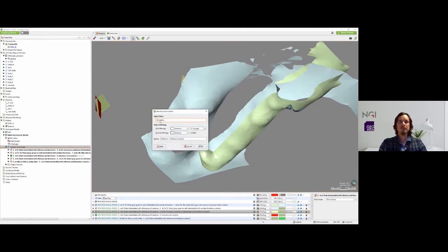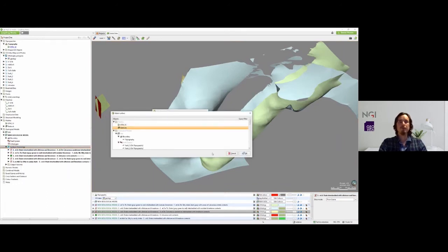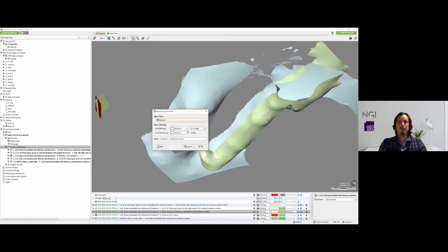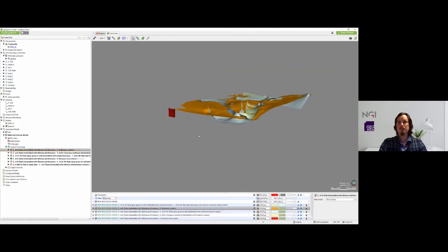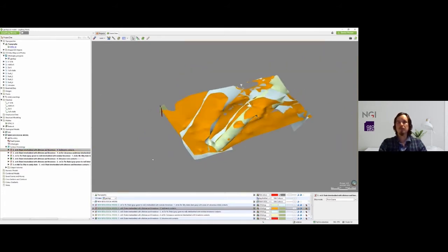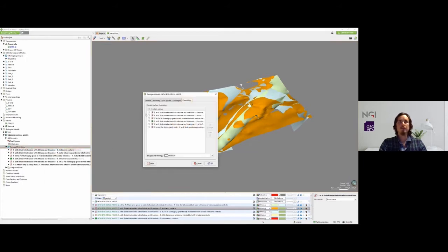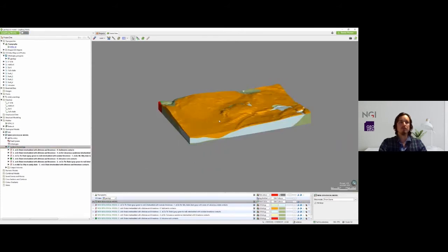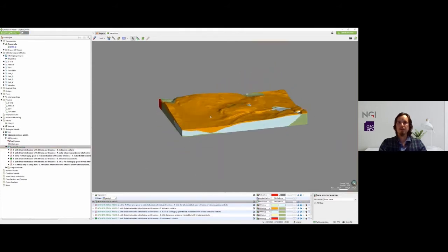Let's add the surface. This one will add from the bedrock mesh, which is created from total soundings. And the soil is the youngest boundary in the model. Okay, so now we have all our surfaces, and now we gotta open them and activate the surfaces to build the volumes for the model. There we have the model.